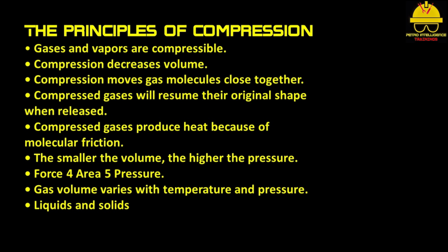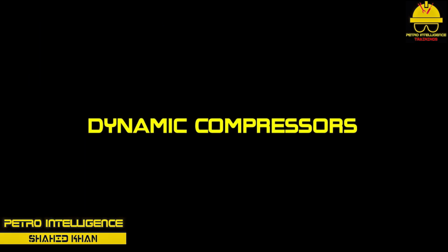Compression decreases volume. Compression moves gas molecules close together. Compressed gases will resume their original shape when released. Compressed gases produce heat because of molecular friction. The smaller the volume, the higher the pressure. Force divided by area equals pressure. Gas volume varies with temperature and pressure. Liquids and solids are not compressible, except under tremendous pressures.